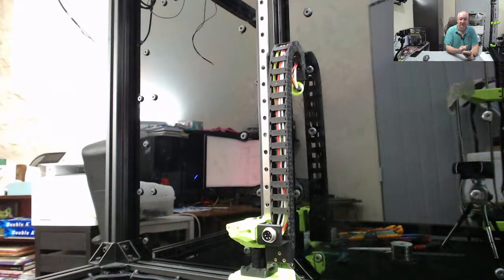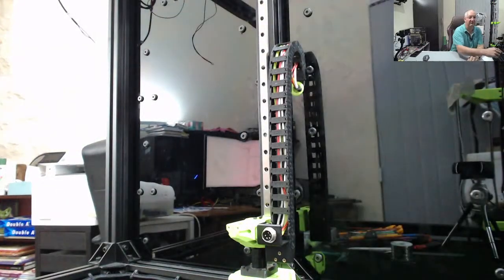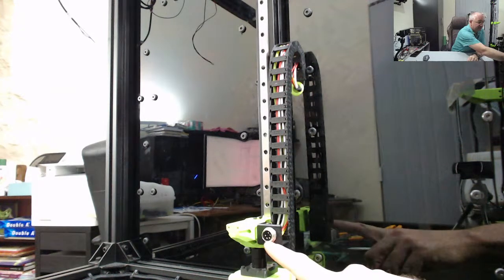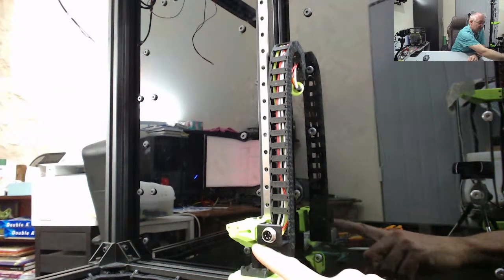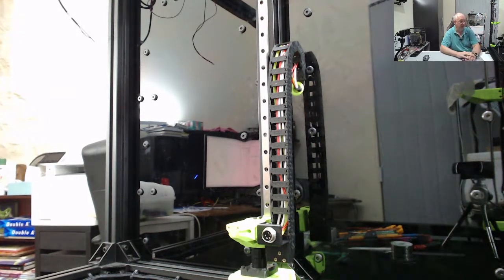Okay. So in order to do that, I've taken my cables, which would normally go straight from your bed heater, from your bed to the back of the printer, and I've put a connector in between. Now I need to test this connector, and we'll see how it does. Apparently that connector can handle up to 8 amps, which is more than sufficient for what I need.